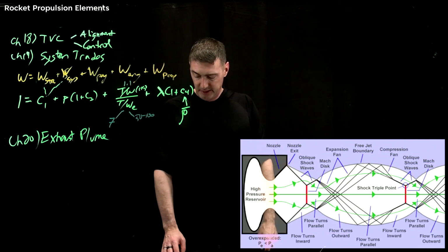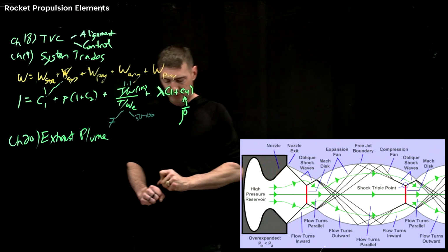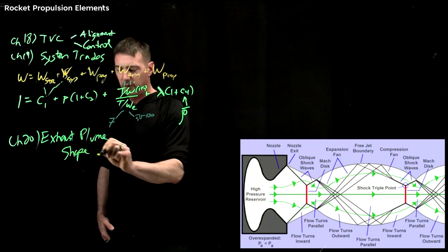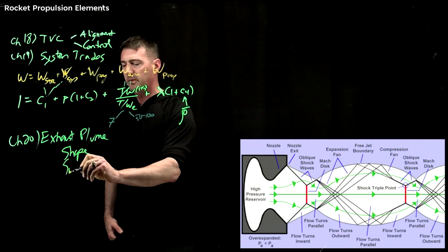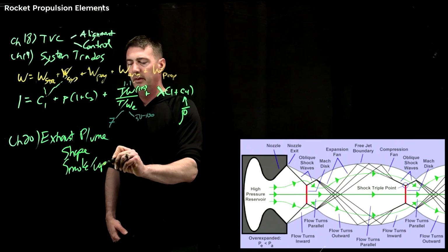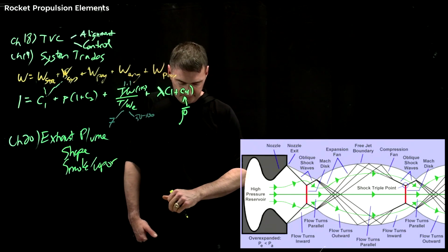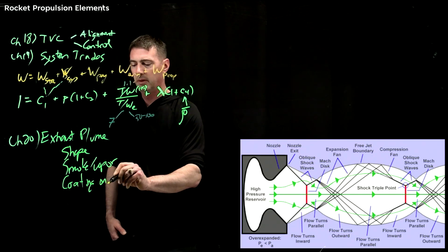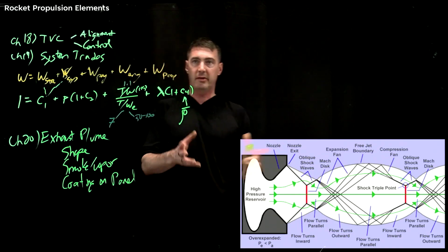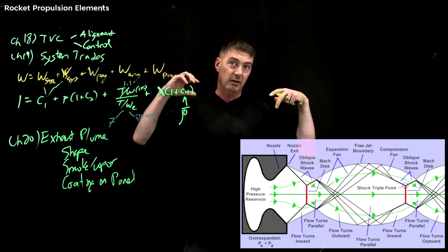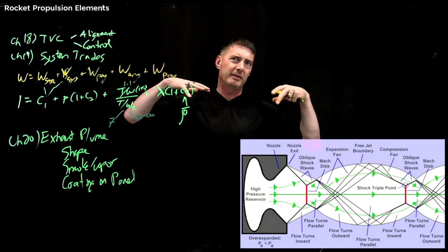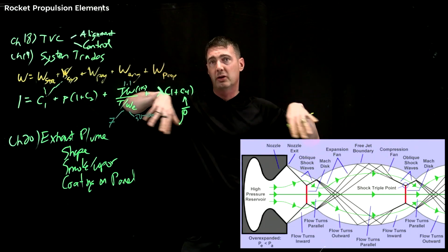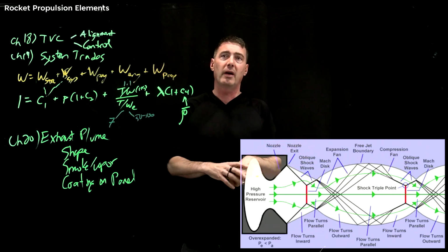But the discussion goes beyond this, not just the shape. We'll talk about the shape, but it also talks about things like smoke and vapor. So it's a good discussion. From a spacecraft, you actually do have to worry about coating on panels. If your engine is firing, some of that exhaust plume may get back to your solar arrays. Again, you're not thrusting very much, you're not moving very far. And so that exhaust plume could, especially if it's electromagnetic, circulate back, following some of the magnetic field lines you've got to watch out for.